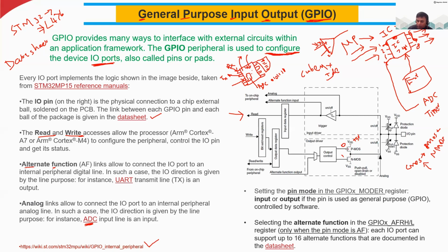So this plus 5, if it's turned on, then this will be short circuited, the drain and source. Then this VDD will travel to this node via this path, because you are applying the gate signal. And after reaching this one, the logic high will drive at the output. So this is the transistor logic. The same logic we are using here also in GPIO. Internally, it's happening in this microcontroller.